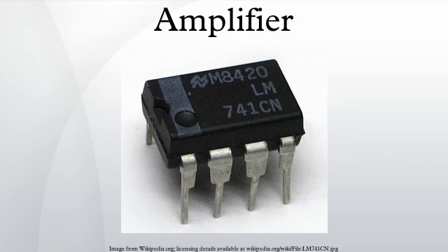Class F can be driven by sine or by a square wave. For a sine the input can be tuned by an inductor to increase gain. If Class F is implemented with a single transistor, the filter is complicated to short the even harmonics. All previous designs use sharp edges to minimize the overlap.